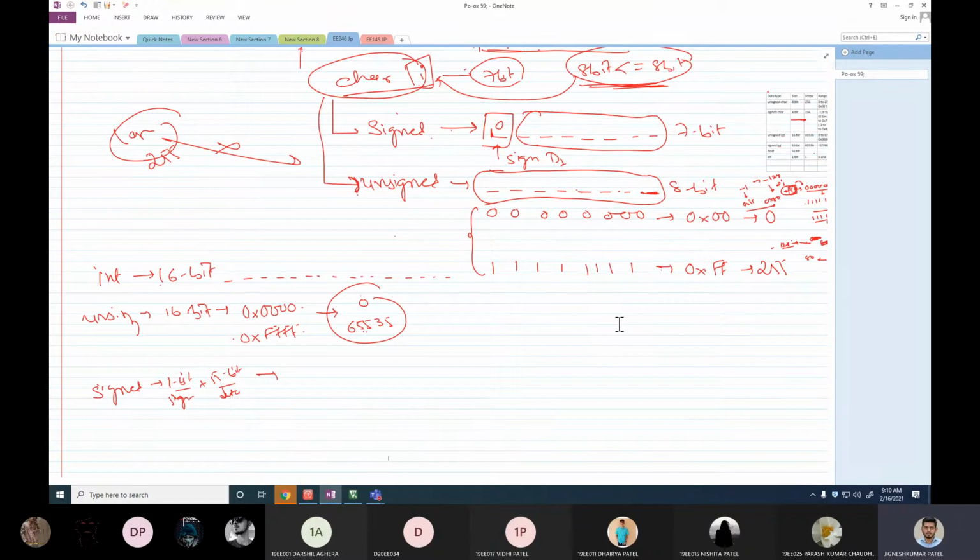Basically, whenever we discuss C programming in 8051, that C programming is known as embedded C, because it is somewhat different from your regular C programming. You have some extra keywords. For example, SFR is an extra keyword, SBIT is an extra keyword. There is one more keyword that is only related to 8051. You will never see these kinds of keywords in general purpose C language. SFR, SBIT, and interrupt are the three. We haven't touched interrupt yet, but we'll come to that at a later point.